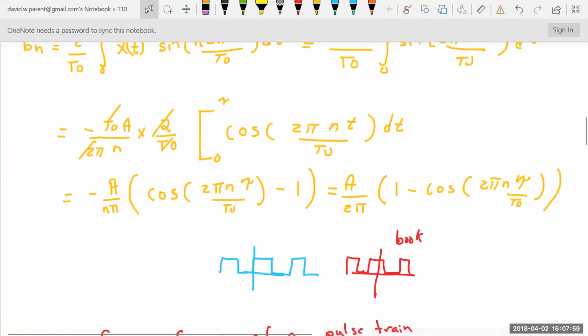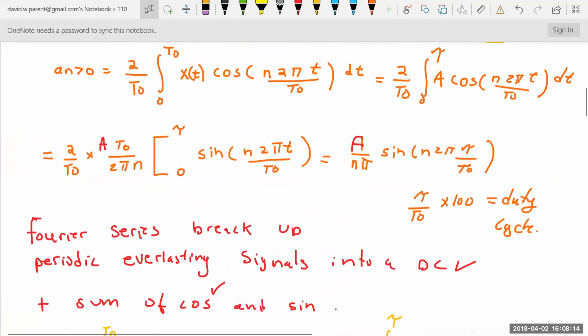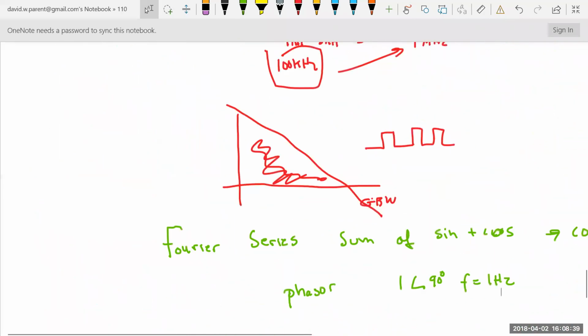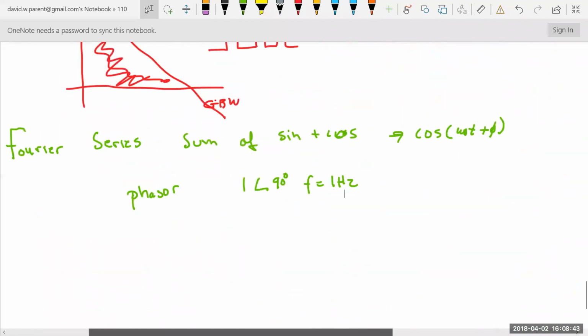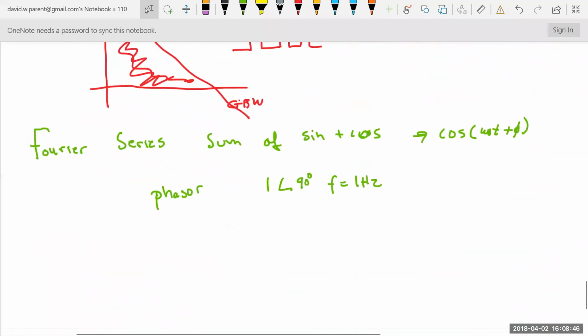So right here is ultimately just the magnitude. This bit's the magnitude times the sine wave, and this part here is just the magnitude times the cosine wave. So you have a sinusoid, and in the A and B, there's no phase, right? When you combine it into one, where you have the magnitude of both A and B, then you get a phase. So really, back in 98, right, you learned phasors. But the Fourier series is just take a signal and break it up into phasors. That's it, right?